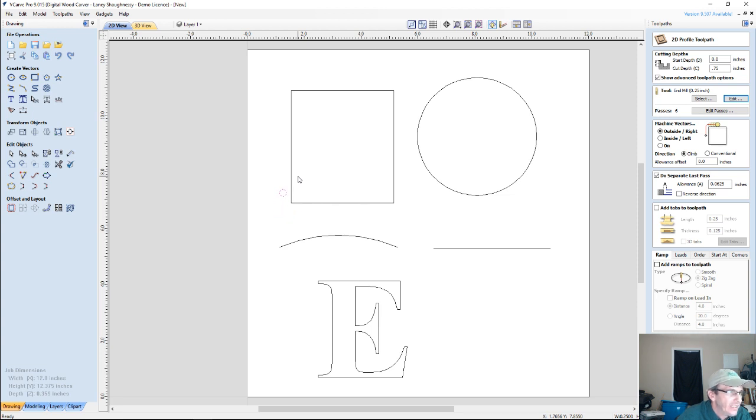On that very last pass, it's going to step back over to the line and make a full plunge all the way down and do a single cut on the line all the way around, cutting our part out. And what that does is we have our full cutter taking that full last pass, and instead of stepping down, it removes or eliminates those witness lines that we would have. Provides us with a much cleaner edge that we then have very little sanding and things like that to deal with, especially if our router is just slightly out of trim.